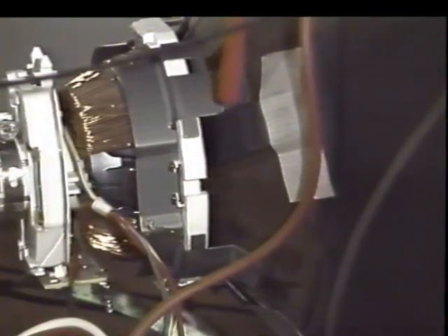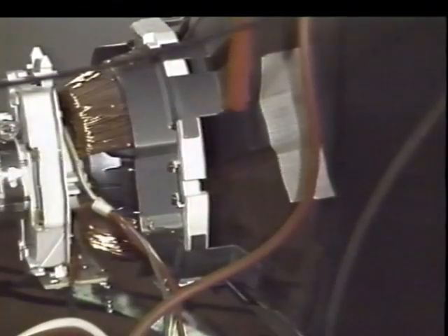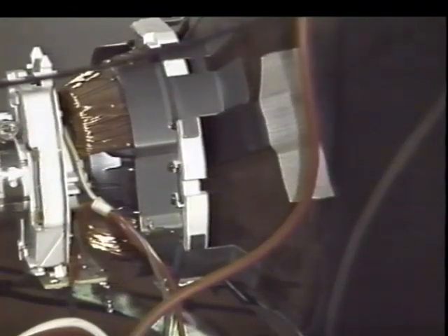Select a crosshatch pattern from your video diagnostics and observe the areas at the corners of the screen. Chances are there will be some divergence of the colors here. It is almost impossible to avoid. To minimize the divergence, you will move the plastic wedges that are inserted between the edge of the yoke and the CRT. This will change the tilt of the yoke in relation to the tube, reducing the convergence errors caused by the beams not striking the faceplate squarely near the edges.